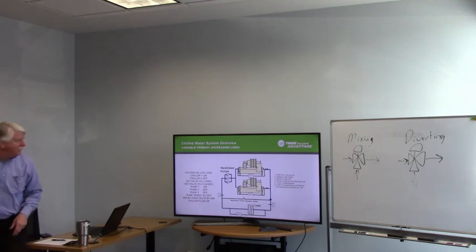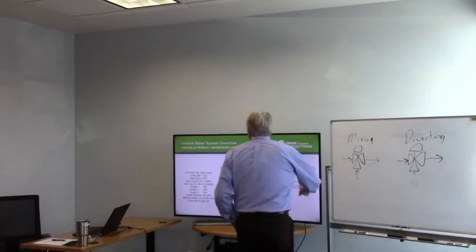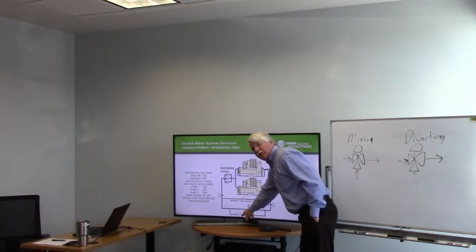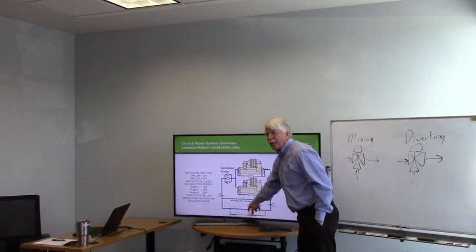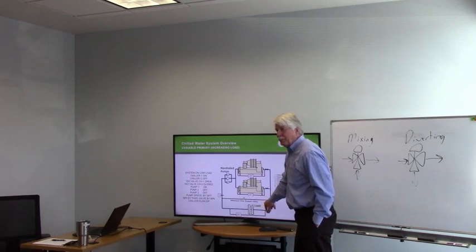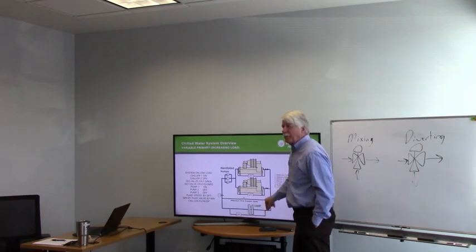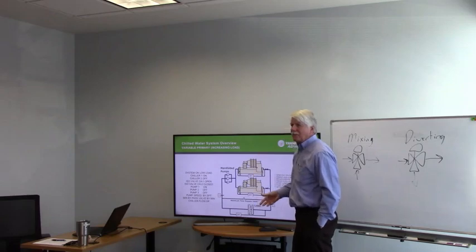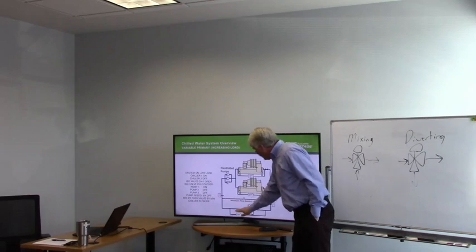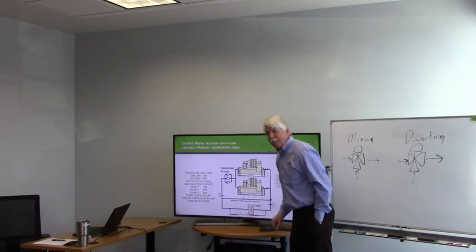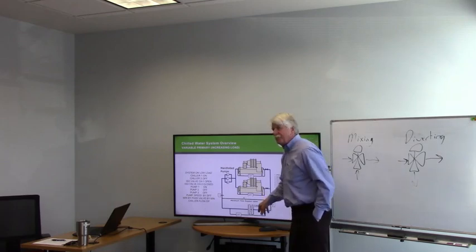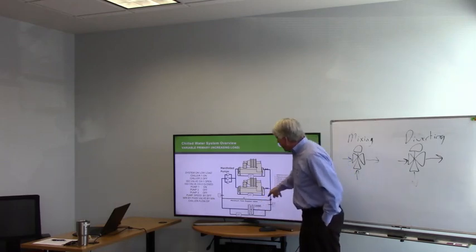So that means the only thing that controls the speed of those pumps are these DPTs out in the system. Everybody see that? And that is so critical because people keep wanting to try to change the speed of the pump because of this. No, the speed of the pump has to maintain the DP out there.